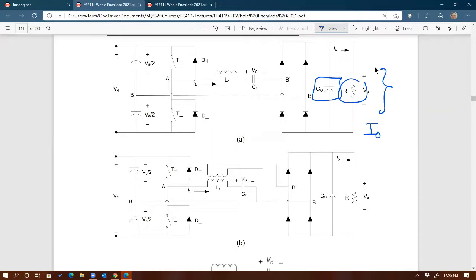So anytime you have output voltage, which you will, you're going to have current, right, by Ohm's law. So when none is conducting over here, there's no energy being delivered from the source to the load. Therefore, this is going to be open, and then it's connected to the source like I drew earlier, like that. And then on the load side, this is going to be a short, right?